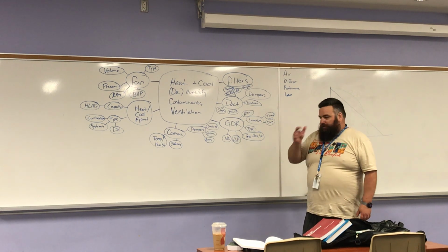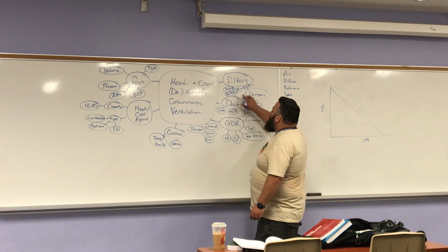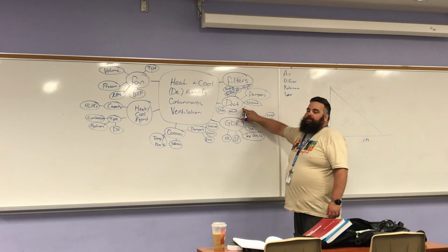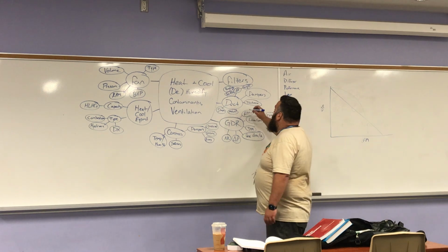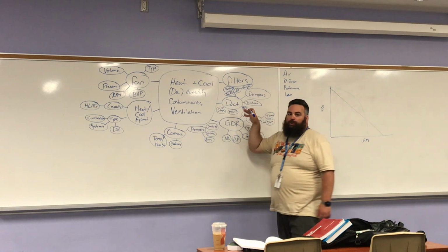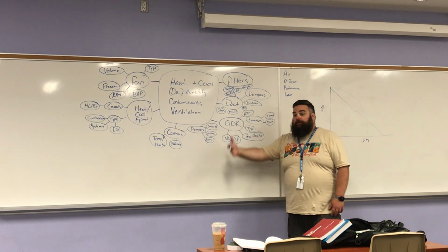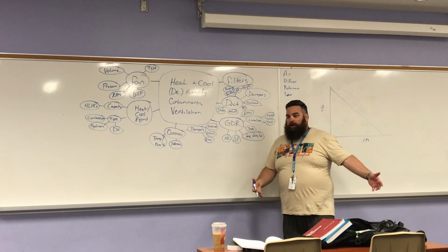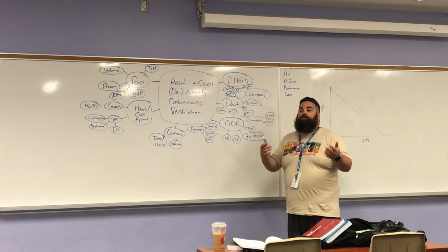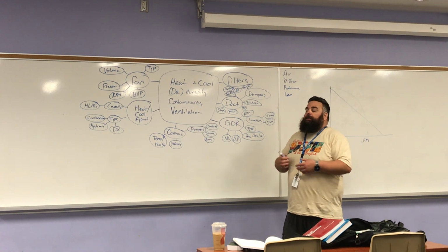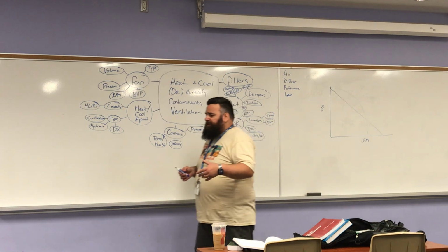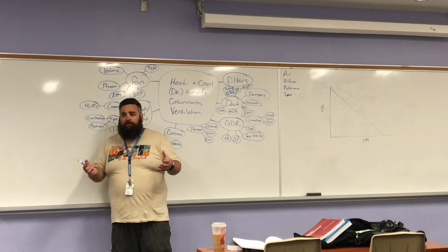Connections, fittings. So I'll keep that under delta P. One thing that relates to delta P, but I'm going to give it its own branch, is PSI, or internal pressure in the duct. Okay? The higher the delta P, the more pressure we need to start with. The higher the pressure, the more it's going to want to leak out. So we have to improve our sealing, okay? And we'll see this more as we discuss how duct is connected to each other, okay?